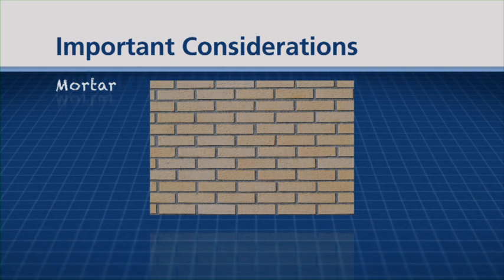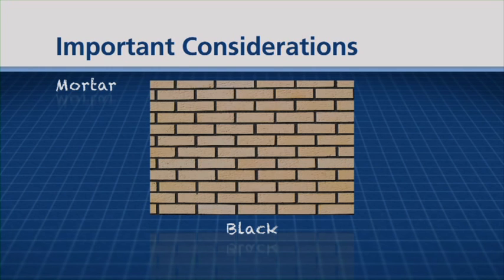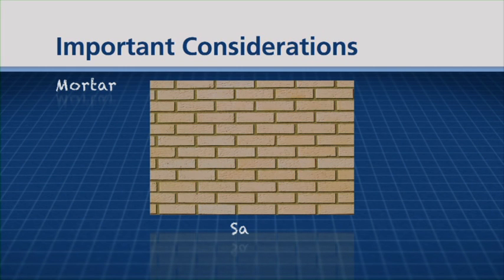20% of a wall in standard stretcher bond is made up of mortar, and it is therefore important to consider the type of mortar used, as it can have a big impact on the overall look and finish of a wall. Also consider the existing brickwork you are matching up to, as both the bricks and the mortar will have weathered from its original appearance.